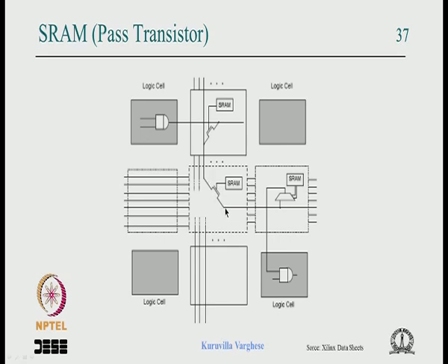Okay. Now the problem with this kind of SRAM FPGA is that it cannot remember; the state of the gate of the NMOS transistor is not stored permanently. So at every power on, this needs to be programmed. So if you look at what can hold a bit, a single bit is a flip flop. So at the gate of each pass transistor is a flip flop, and when we say we program, we are programming the flip flop as 1 or 0.